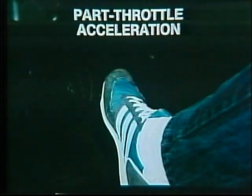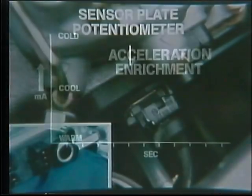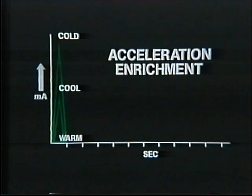Part throttle acceleration considers economy and emissions, adding just enough enrichment for good drivability. For a warm engine, it's handled just like KE Jetronic systems. But for a cold engine, the KE sensor plate potentiometer signals how fast the sensor plate moves as airflow increases and how far it moves. From this input, the control unit sends a compensation output to the pressure actuator. For about 1 second, current increases, depending on sensor plate movement and on engine temperature and RPM. That's important for drivability of a cold or cool engine.